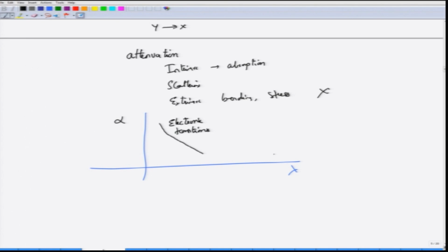You will see that at longer wavelengths there is an intrinsic absorption, that is, at the IR region there is an intrinsic absorption here, this is the UV region. So, this absorption keeps on increasing beyond around 2 to 2.2 micron for a silica fiber. In between is what is called the low loss window, in which you will find some amount of vibrations. These are because of some metals which are present in the fiber, and then you will also see some water peaks which happen because of the impurities in the form of hydroxyl ions, which are introduced when the fibers are being fabricated. Connecting this would be the low loss window. In fact, modern methods have almost eliminated these hydroxyl peaks, or the impurity ions, water impurities, and thereby lowered the losses.